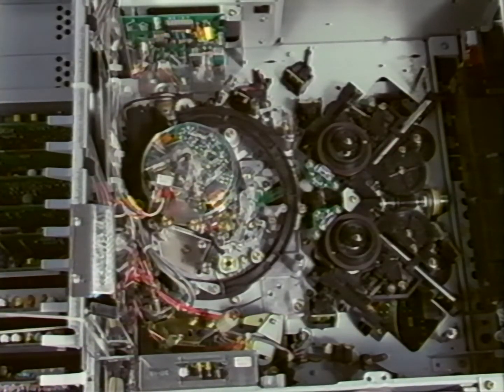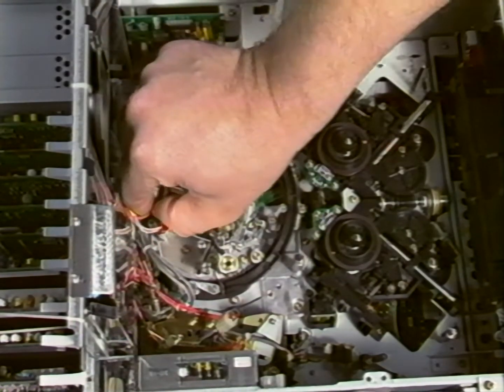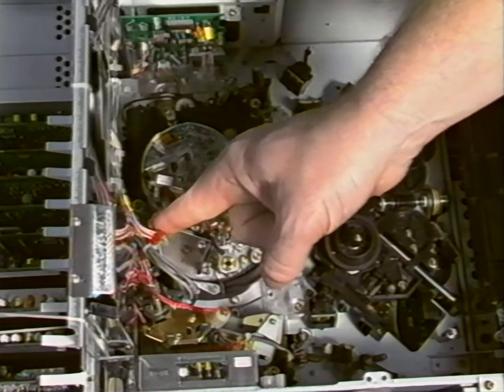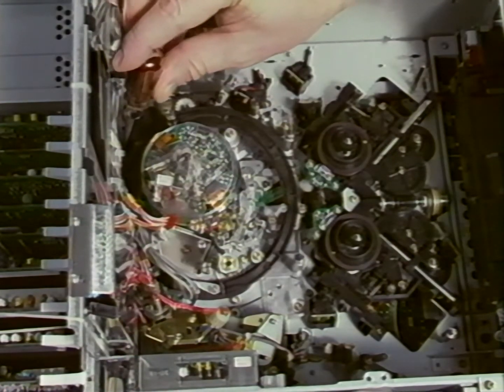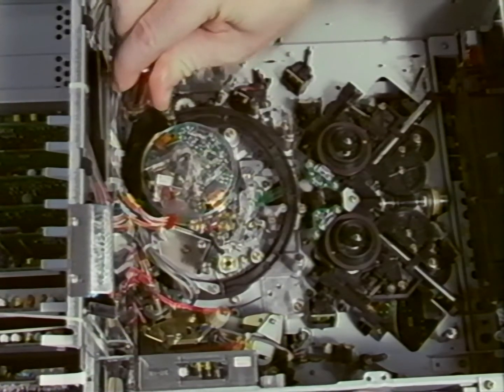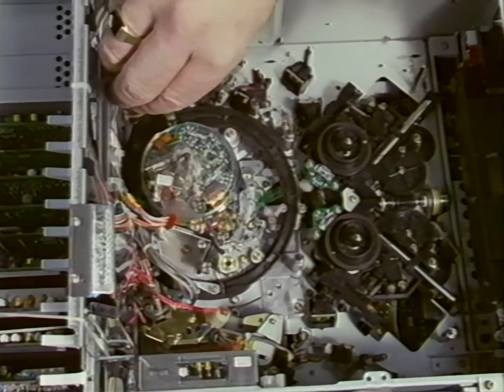Disconnect the two leads going to the brush assembly. Loosen the two screws of the gearbox and back the gearbox out of the way so it is no longer engaged with the threading ring. Finally, loosen the fixing screw of the ring roller located behind the drum and release the hold on the threading ring.